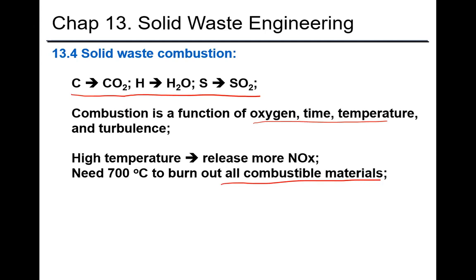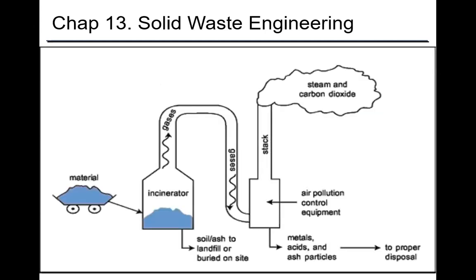It's quite a complex scenario because the waste is not homogeneous, right? It's not uniform like coal particles. You can have a lot of plastics, let's say wood or paper. Each of them will have different combustion properties, okay? Furthermore, you generate a lot of toxic air. So that's why in these garbage incinerators, when we put in this trash and combust it, there has to be air pollution control equipment which removes the particulate matter, the sulfur dioxide, the NOx, and so on.